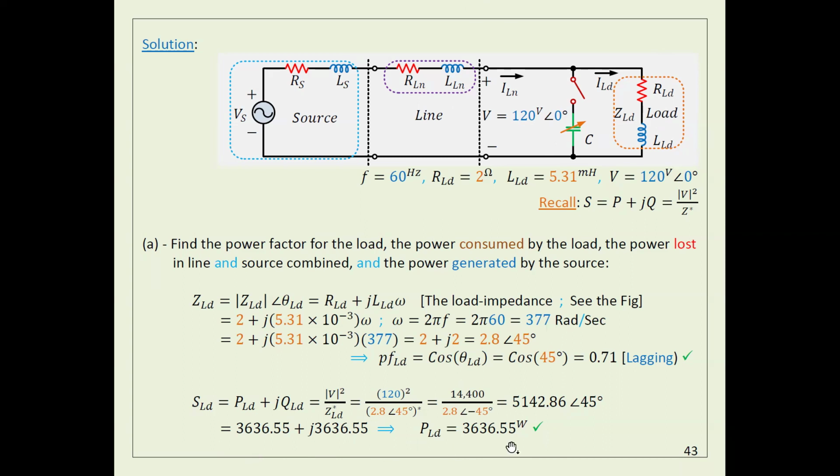Okay, guys. So here, there are two parts. This part is the amount of active power, and this part here is the amount of reactive power. They look equal, or they are equal. By inspection, they are equal, because I think cosine 45 is equal to sine 45. Anyway, because of 45 they should be equal. So now I found the power consumed in this case.